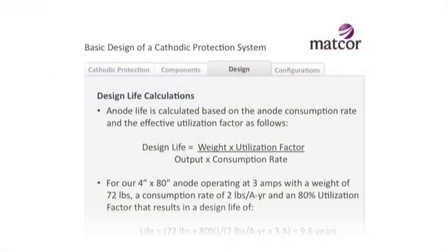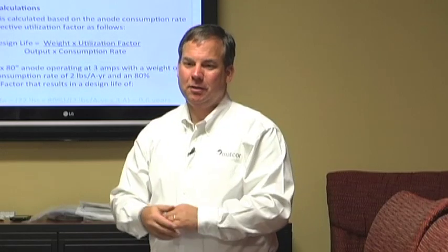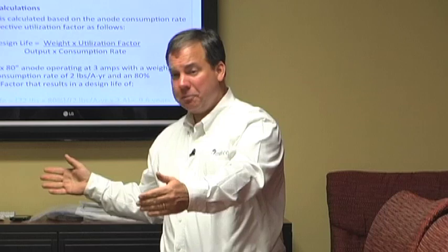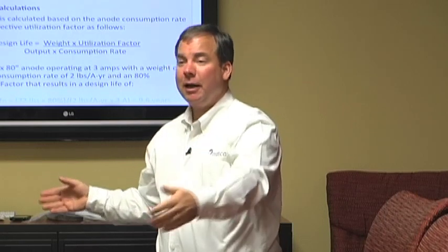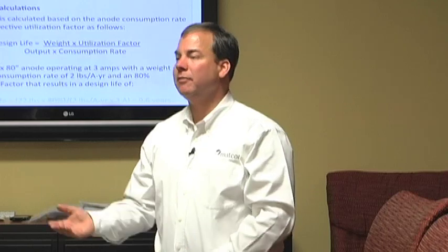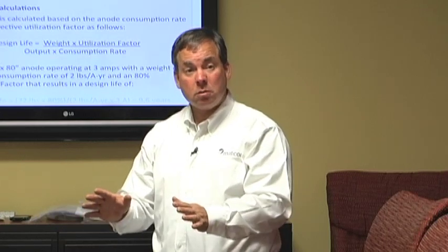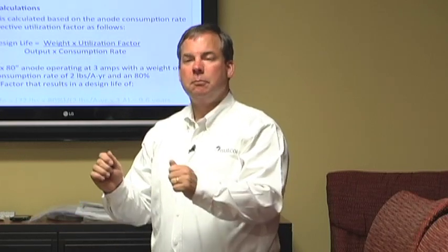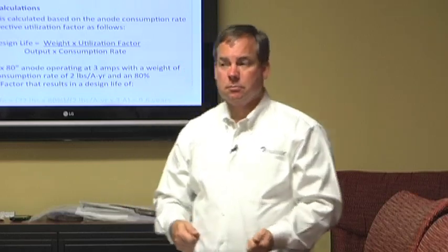Now often we design it for 10 amps, they go out in the field, they find out that 8 amps is fine. Well, that's great, because now it's going to last longer, because I'm not running it as fast. Or you go out in the field and you find out, you know what, it wasn't exactly a 100-foot long sheet pile wall, it was 110 foot long, and it's taking a little more current than we thought it was going to take, and we're going to operate that 10 amp system at 12 amps. Well, that's fine, it'll work in most cases, but it might not last as long as you designed it to.